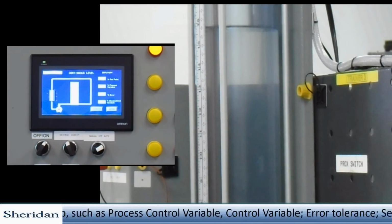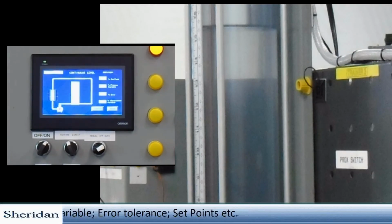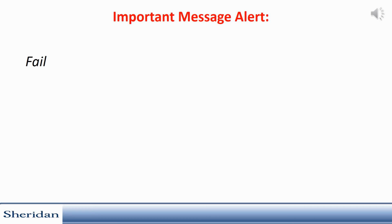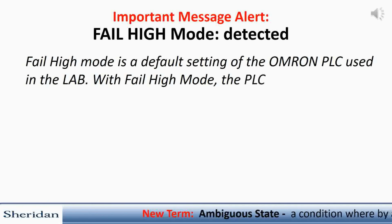When we turn on, you can hear the motor should start to sound like it's trying to run. It's not running because we don't have a set point. So right now our process variable says it's ridiculously high because we're in what we call a fail high mode. Fail high mode is a default setting of the Omron PLC used in the lab.